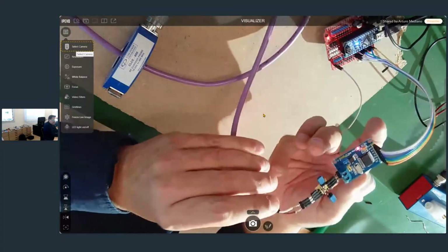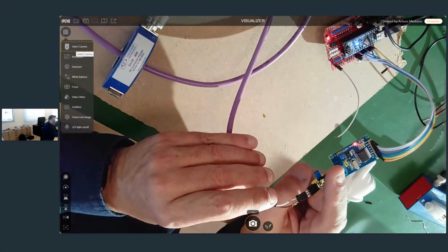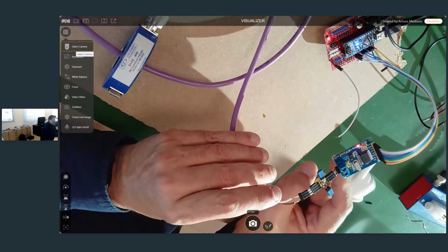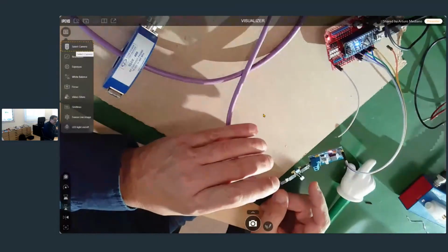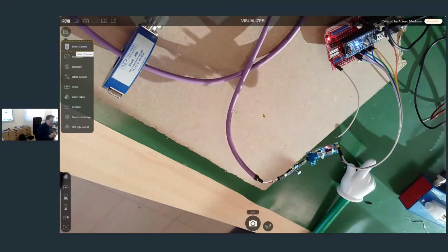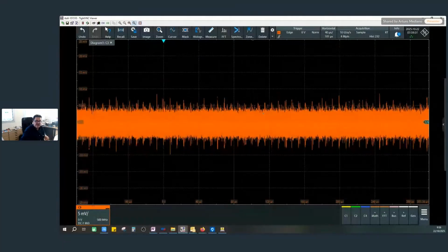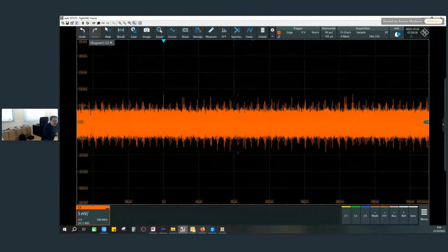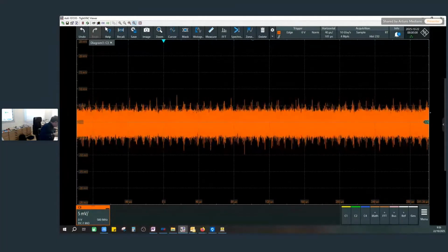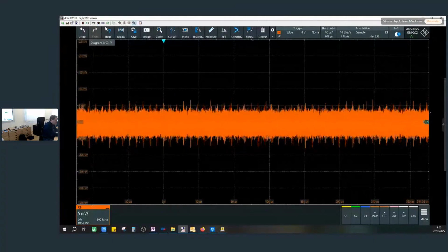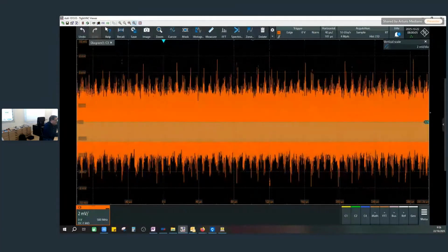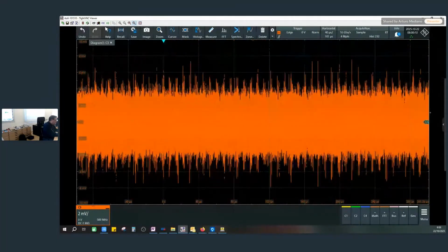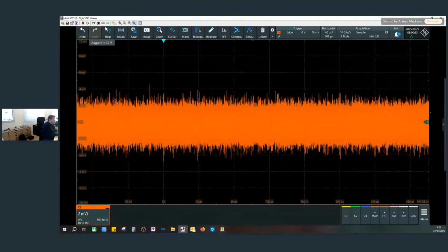series. Remember that this is a situation where I am not able to introduce capacitors from the lines to the chassis, because the introduction of capacitors from lines to the chassis can create signal integrity problems in my circuits. So let's see the screen of the oscilloscope again. You see, this is what I have without the common mode choke in place. And now I am going to remove the jumpers, so let's increase the amplitude. This is without the common mode choke. This is with the common mode choke. 1, 2, 3. Okay, you can see the reduction.